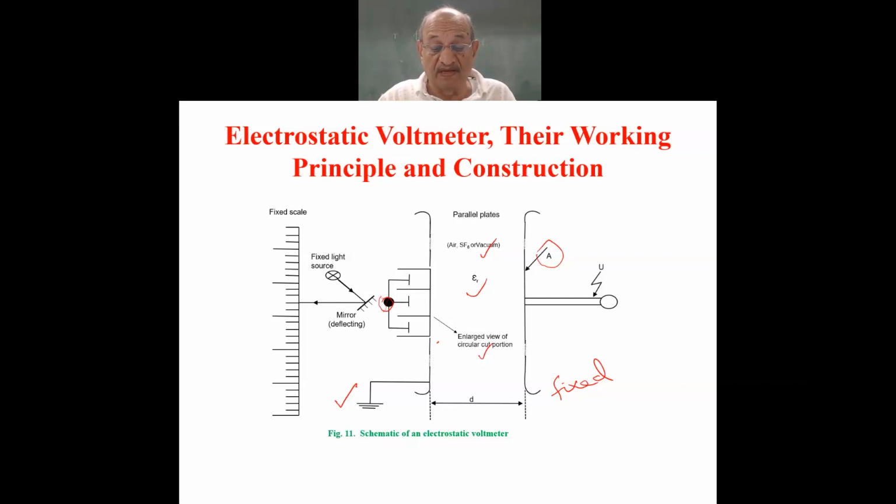This floating mechanism experiences the force, and because of the electrostatic force between the two plates, depending upon the magnitude of the voltage, this rotates, and by rotation it rotates the deflection of the mirror.